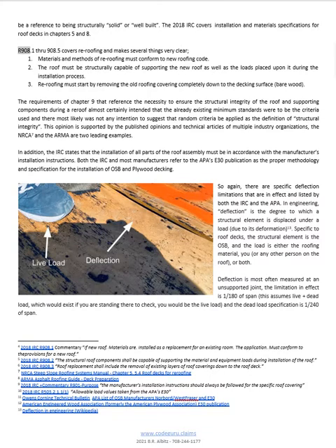R908.1 through R908.5 covers re-roofing and makes several things very clear. Materials and methods of re-roofing must conform to new roofing code. The roof must be structurally capable of supporting the new roof, as well as the loads placed upon it during the installation process. Re-roofing must start by removing the old roofing covering completely down to the decking surface, bare wood.